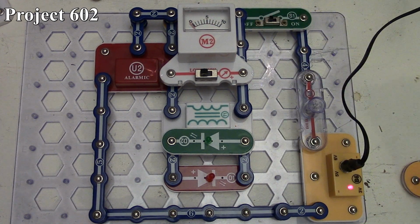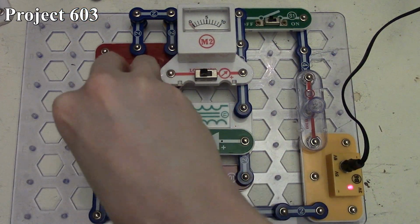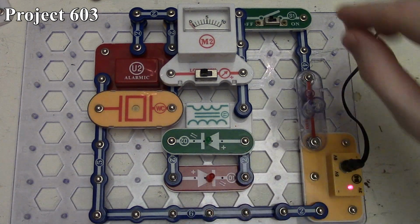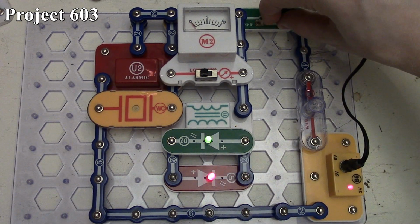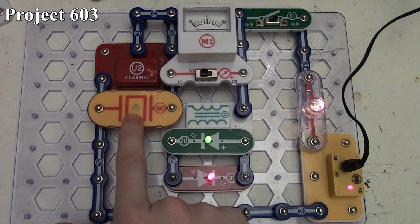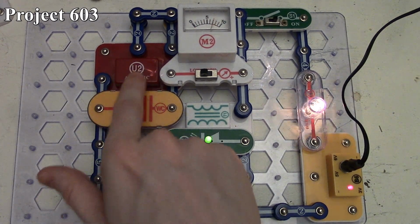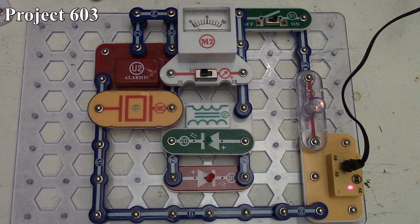Now project 603, we're just going to take the whistle chip and replace it where we had our motor. So now we're going to hear more of the alarm IC output. It still pulses at about the same rate or so as the previous project, but now with the whistle chip in place of the motor, we're now getting more audible output from the alarm IC. But of course the whistle chip does not behave like a motor, so it's not creating any kind of AC voltage across our transformer here.